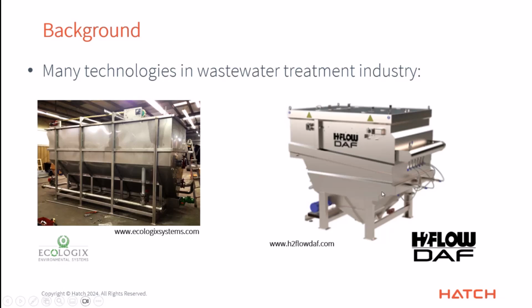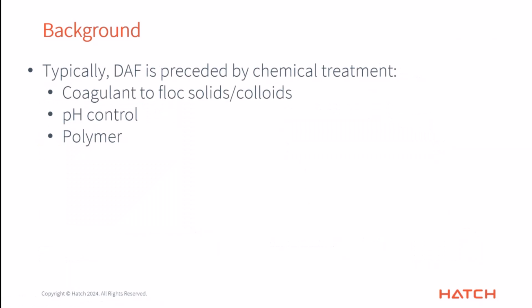You have a reactor here, as I mentioned. You have a way to inject the air and create the bubbles. And then you also have a collection of solids at the bottom, and most of the solids will be captured by the bubbles floating to the surface. And as you can see, there's usually some sort of conveyor moving the solids off of the top of those as well. Now, normally a DAF system is not just the DAF, actual physical DAF unit by itself.